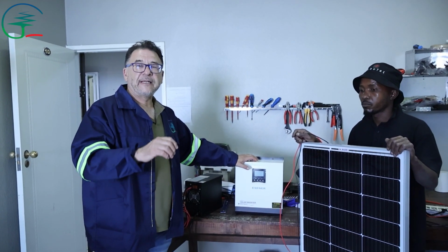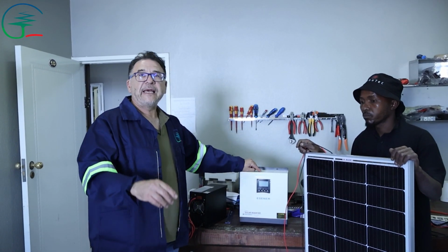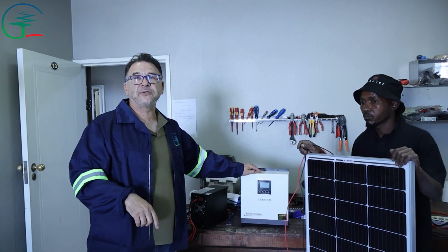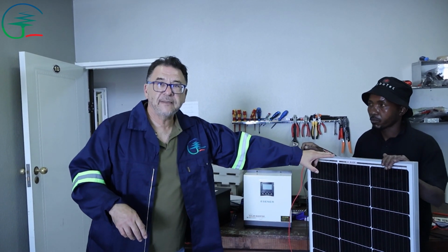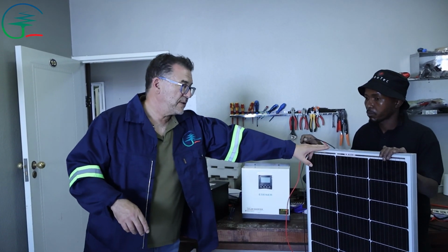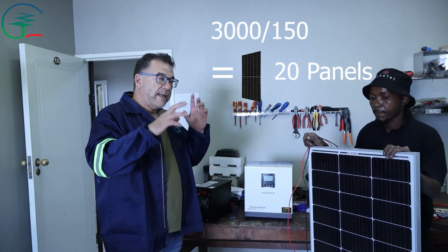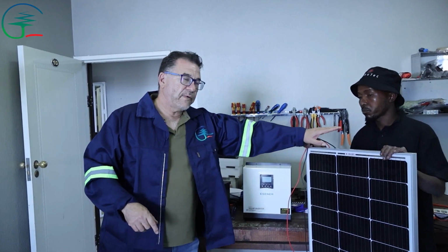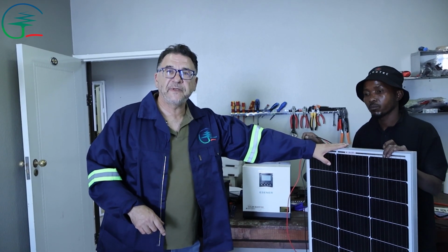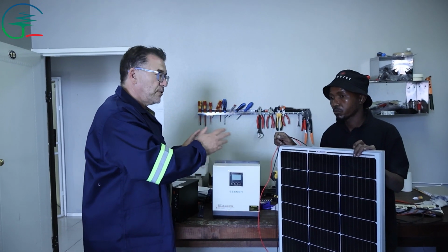However, the limitation is that this is only a 3000 watt inverter. Hence, as I told you at the beginning, you divide 3000 by 150, which is 20 panels. So you can only connect 20 panels to this inverter if your solar panel is 150 watt, with the values I've explained.